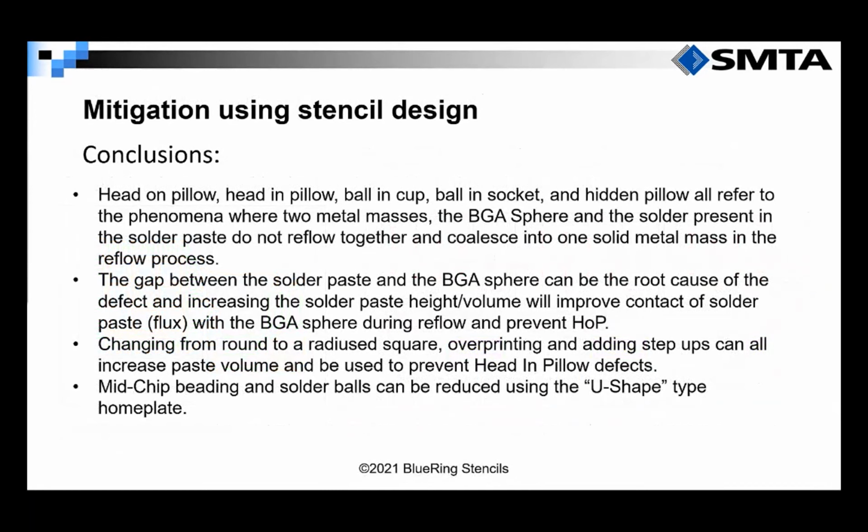Head and pillow, or head-on pillow, along with these other names, all refer to the phenomenon where the 2 metal masses, the BGA ball and the solder, do not reflow together and coalesce into one solid metal mass during reflow. The gap between the solder paste and the BGA sphere is the root cause of the defect, and increasing the solder paste height, making sure there's always flux present throughout the reflow process, will prevent head and pillow.